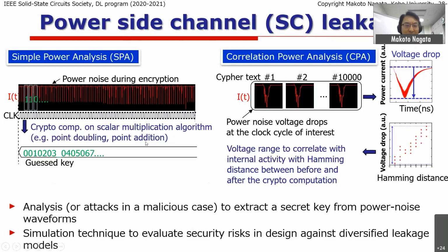Those are the fundamental arithmetic processing units used in public key algorithms. Once again, public key crypto needs more than thousands of clock cycles to complete. On the other hand, for private key crypto like AES, depending on the design, often only 10 to 20 clock cycles are used for a single encryption or decryption. So data can be encrypted or decrypted very efficiently using private key crypto.